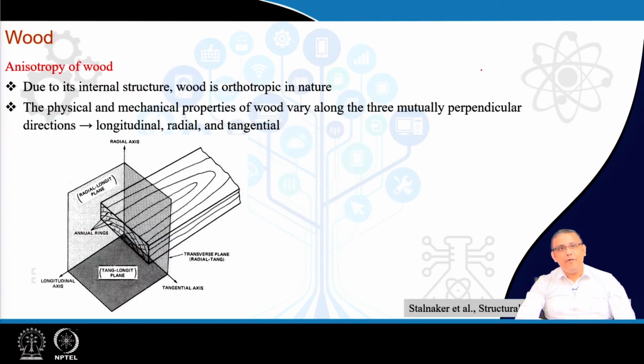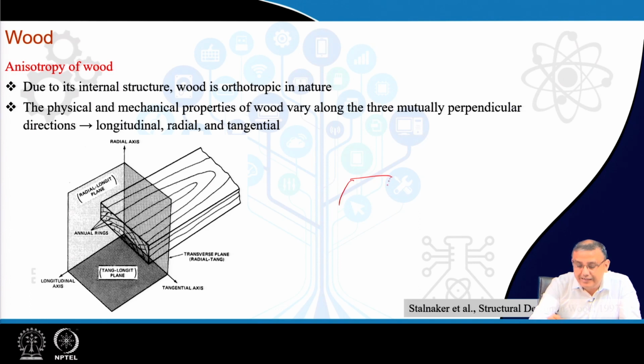Now, another important point I already mentioned at the beginning is that wood is not isotropic. I already mentioned that isotropic materials are like typical metals which do not have any texture, like in the cast condition, with small dendrites or whatever like that. Then we expect those metals or alloys to be isotropic. That means the properties should be the same along all directions. A typical example, if I draw a structure like this.